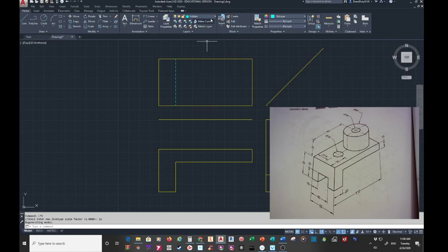Well, guess what? I'm going to draw me a line. It doesn't matter what layer I'm in, and it just so happens that these are all lined up on the center. Then I can use my offset command, and it says that from here over to here is where the center of this guy is. And then it says the next one is 80. And so there's the center of the boss, there's the center of the circle. So I need to go back and change back to my object layer.